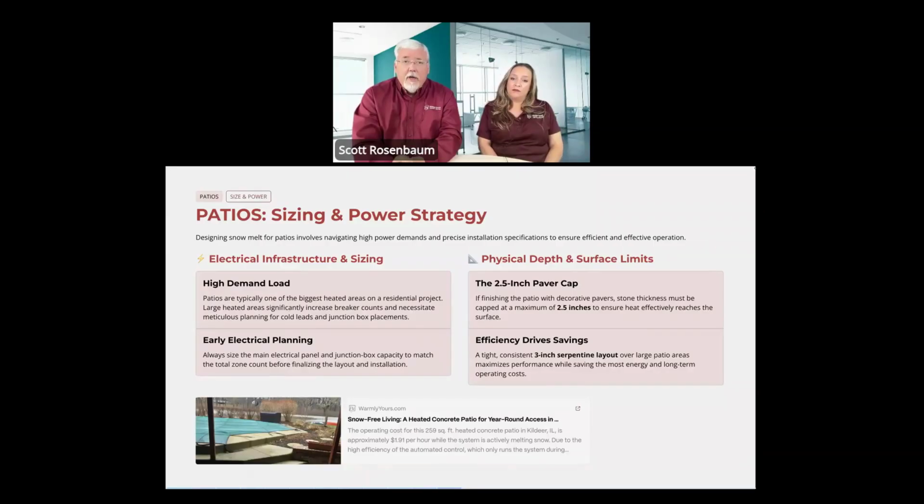If you have a 3-inch paver, it's not going to cause the system to catastrophically fail. We get that question all the time: what if I use 3-inch pavers? It will probably work, but it will heat slower because there's more thermal mass. You're heating a thicker object, so it will take longer, and it may not get as warm at the top. We know the system works at 2.5 inches. If you say, I want to use a 3.5-inch paver, that's up to you, and it may or may not work, because I can't tell you, depending on where you are in the country. So you need to make sure that you are doing 3-inch spacing.